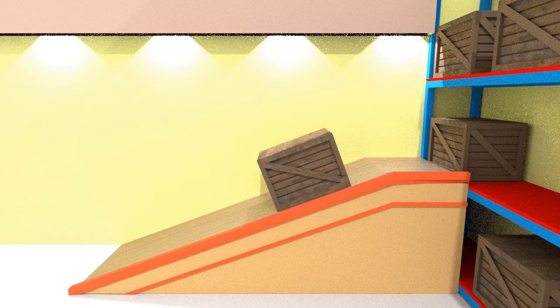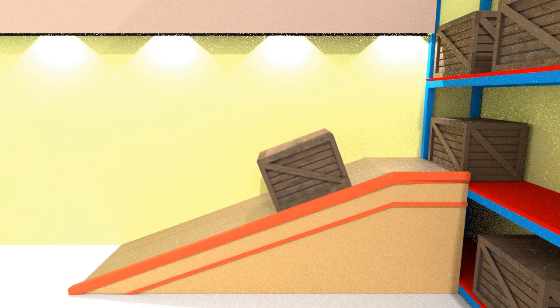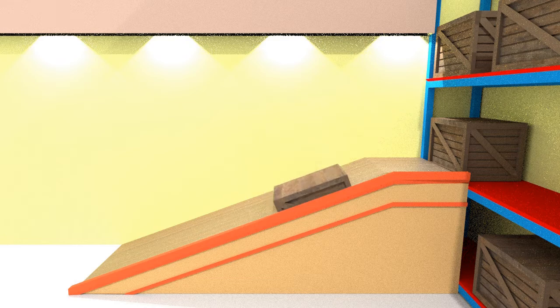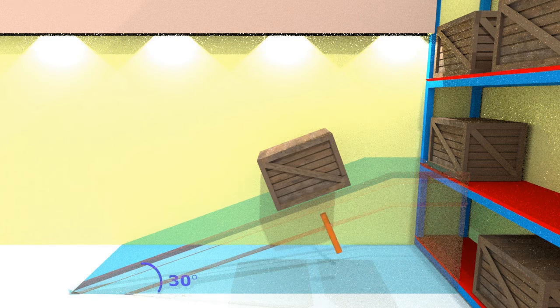As the plane of the ramp is assumed to be frictionless, the box can move in this direction freely under application of force. But the ramp prevents the vertically downward movement of the box, and so a reaction will be developed in the opposite direction, normal or perpendicular to the plane. Other supports like a wall or storage rack are not in direct contact with the box, so they can't influence any movement. Also, the box is lying loosely and no additional external force is applied. So only one reaction from the ramp is acting.